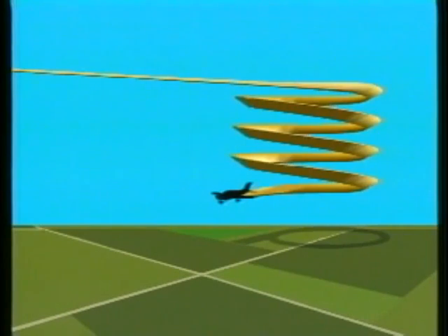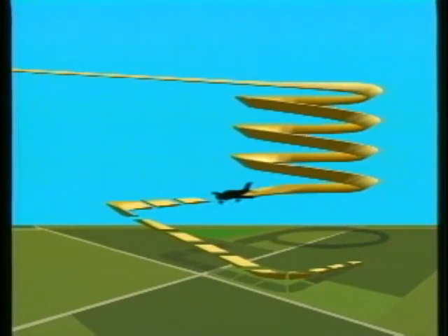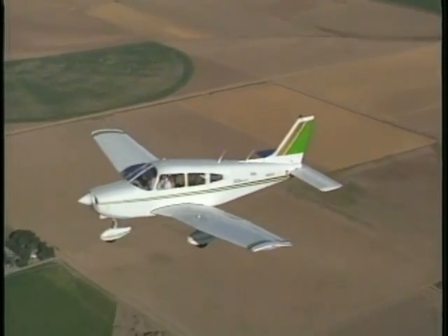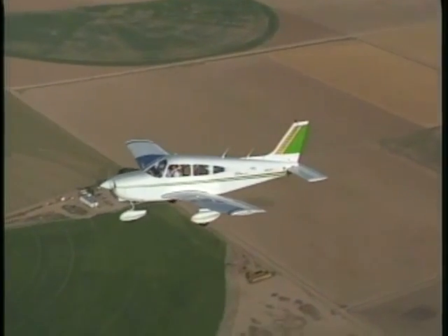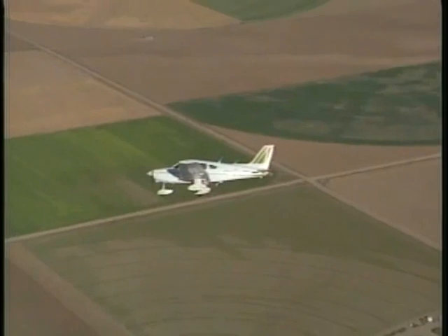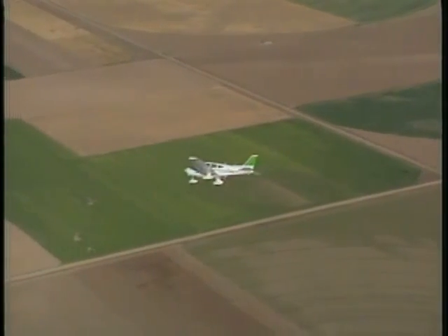Adjust the spiral to roll out on a downwind heading as though you were going to make a normal approach at an airport. During an actual forced landing, you would continue to maintain your desired airspeed and plan on arriving at the key position with enough altitude so that you can land into the wind. The steep spiral is an excellent training maneuver because it helps you develop the ability to accurately control the airplane. In addition, it gives you a way to safely descend to the landing site should an actual emergency occur.